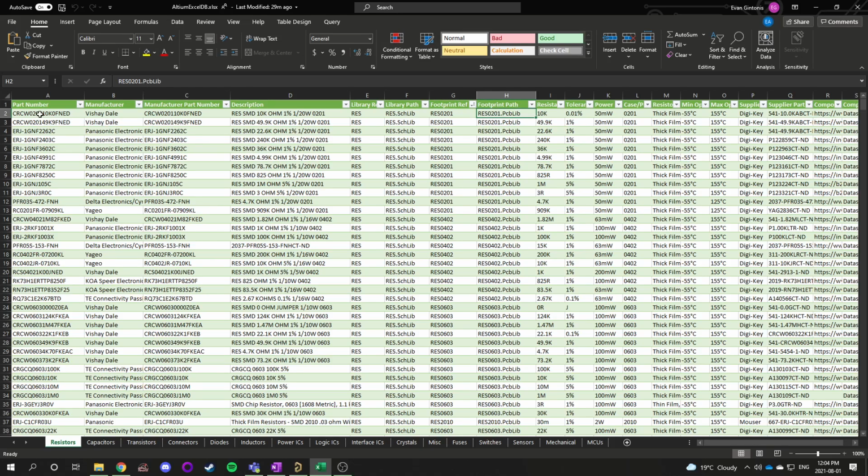So this basically tells Altium, hey, I know we have this schematic symbol for the component, but when we're going into PCB mode, this would be the footprint for the component, or what it would look like in real life. So essentially, we're just linking the footprint to the schematic symbol here to create the full component, so we can represent it in schematic world and in PCB world. So when you're ready to transition and do board layout, Altium is going to have all the correct footprints for your components all there, so you can place them on the board and then route traces around them, connecting them together, which is awesome.